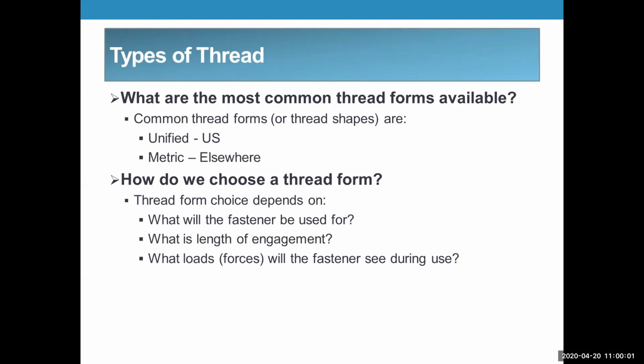That's why they rivet them together. It's still going to take all the vertical and horizontal load that it's designed to take, but it won't add that torsional element to that connection. And that's why they do that, because almost all the loads that are applied are either vertical or horizontal in some way, and that's what those designs are meant to deal with. So that's the reason why.